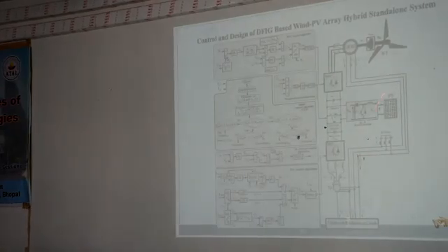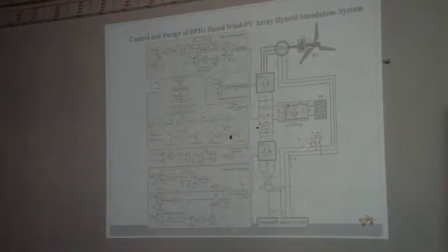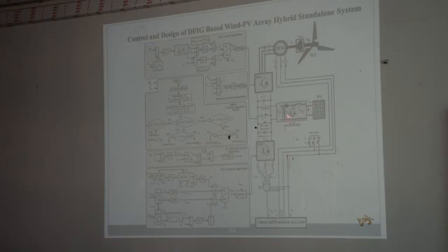So a DFIG like the previous case is used in this case, and a photovoltaic supply system is there. The advantage you are getting here is that you are eliminating one converter. PV is interfaced with the help of a boost converter with the DC link. These two converters are naturally required when we have a DFIG operation. Then this algorithm is there. You can refer to the paper which was published in IECON 2016.